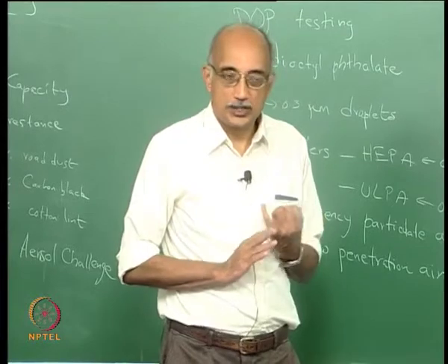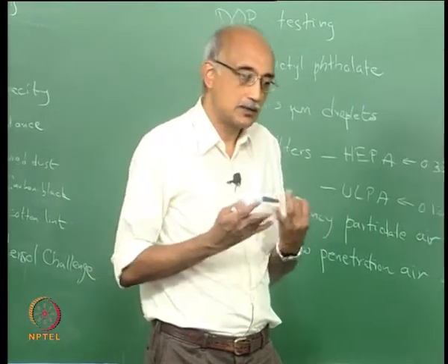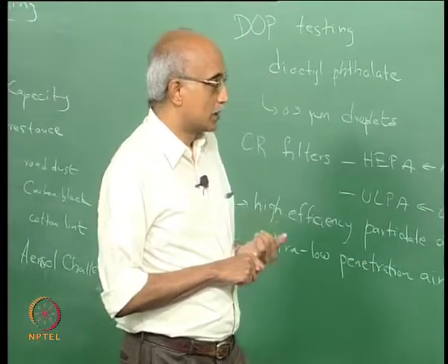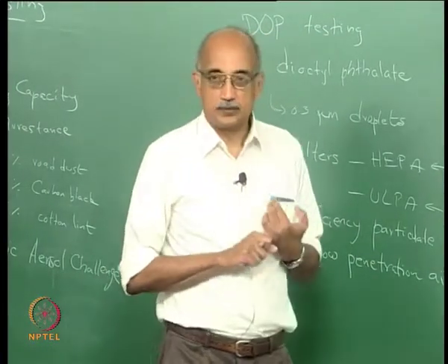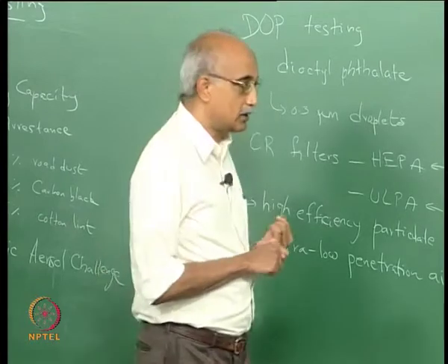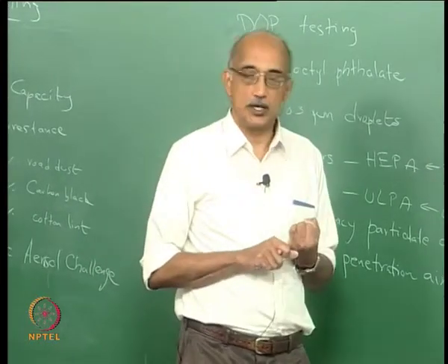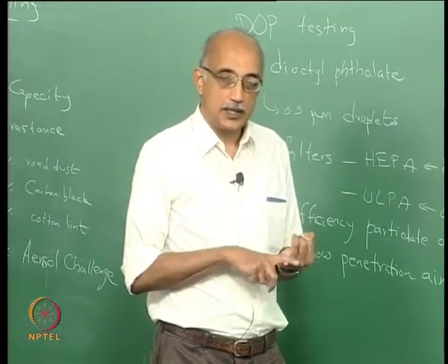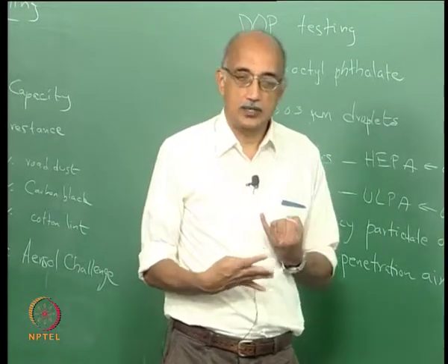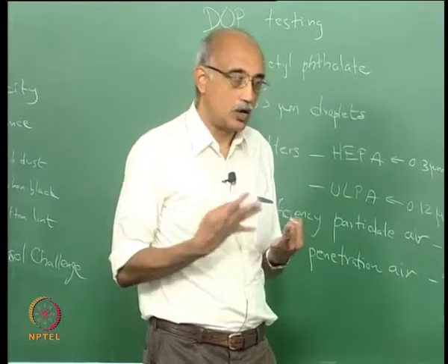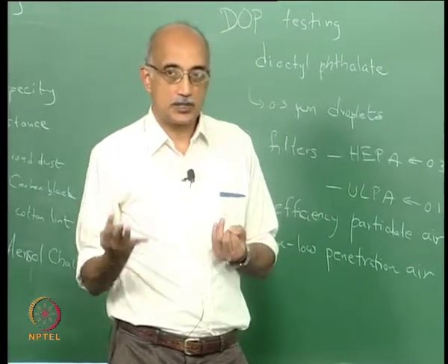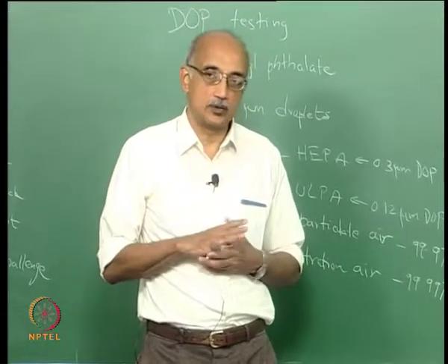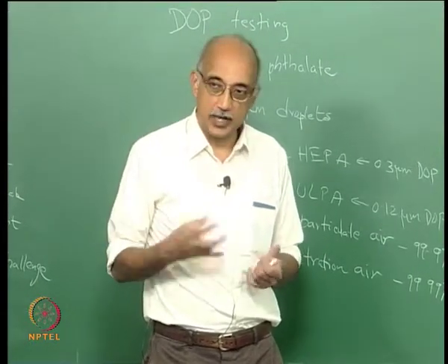I mean, you can use a liquid sieve and sieve particles, but a mechanism like, for example, diffusion, particles are not able to diffuse very fast in liquids because of the high viscosity. But that can be counteracted to some extent by the fact that in liquids the particles have a longer residence time, for the same reason. Because of the higher viscosity, they spend more time in the liquid medium, so the probability of capture is a little higher.